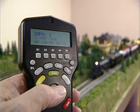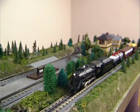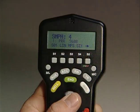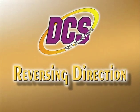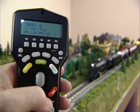There is no neutral in DCS command mode. The default startup direction is forward. Just roll the thumb wheel upward to make the locomotive move forward. The LCD display on the DCS remote will show you the engine speed in scale miles per hour. Because there is no neutral in command mode, the direction change cycle is shorter than in conventional mode engines. There are two ways to change directions in command mode.